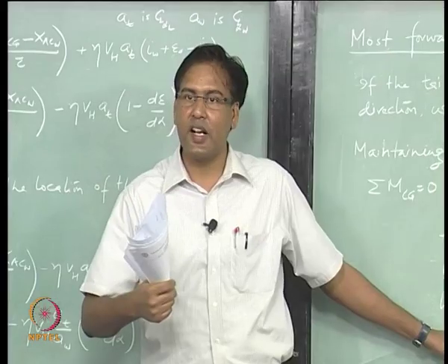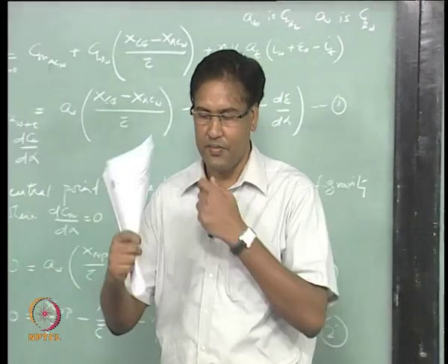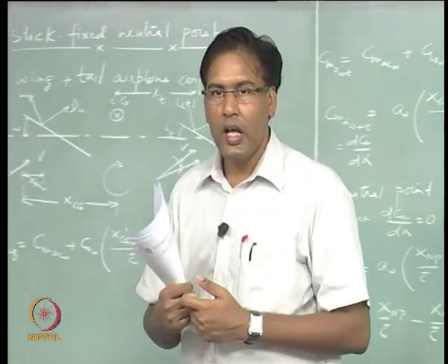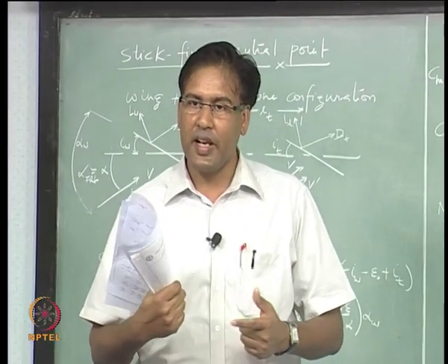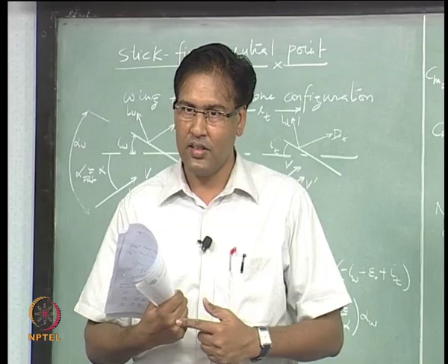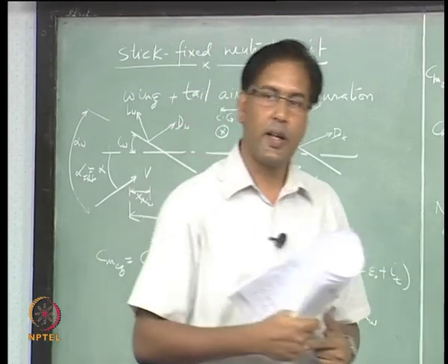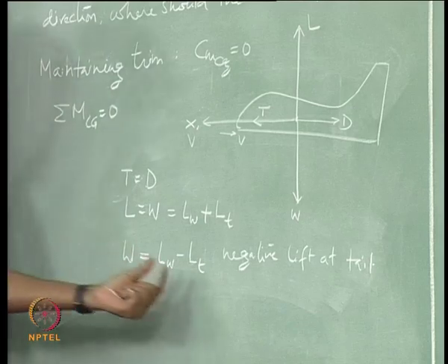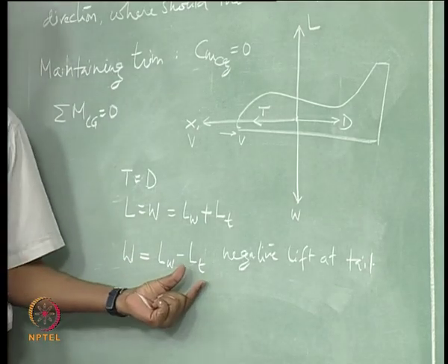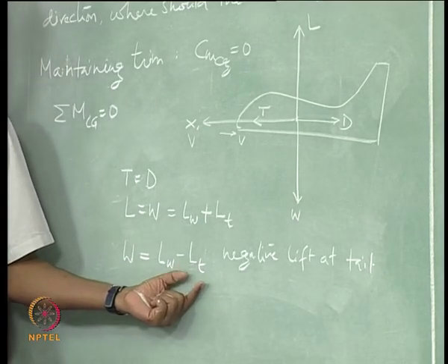To start with, we said that the tail is always going to have a symmetric airfoil, right. What is going to change the camber of the tail? Elevator.